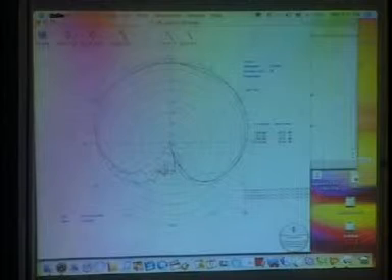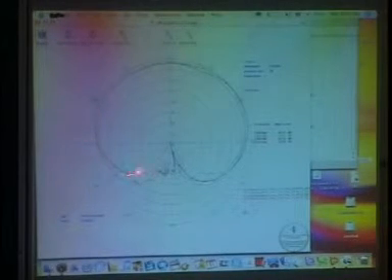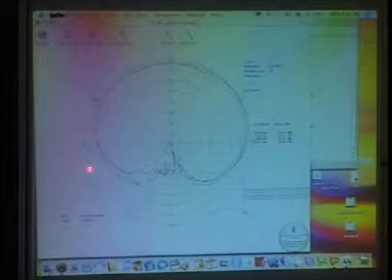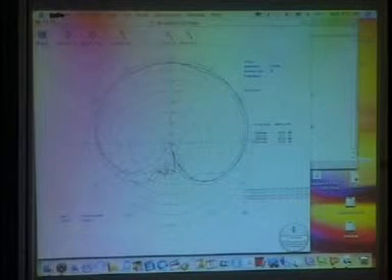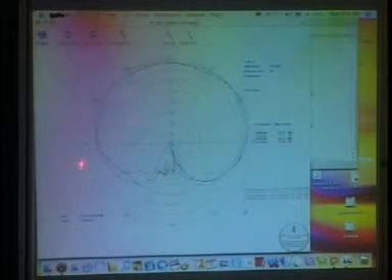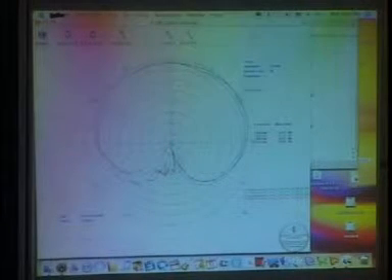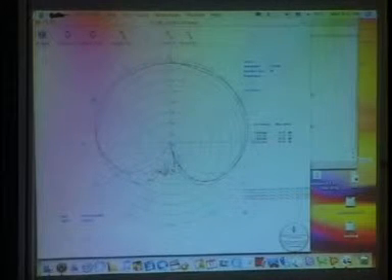We wanted to slightly shrink the antenna so that the interference zone is less. That's why you can see it is tapering off quite fast. Compared to what I showed in the morning, which was coming almost up to this much, here we have slightly shrunk this, so that if you have another antenna of almost this size, that would do the job. For Chandrayaan we wanted a much wider coverage, so that is why we have made it like this.